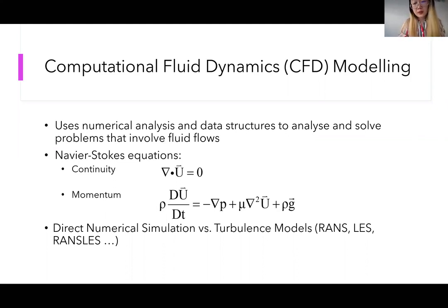And here come a lot of turbulence models. And I'm sure people are very familiar with the Reynolds-averaged Navier-Stokes equations, which is called RANS, and also the large eddy simulation called LES. With RANS, the way that RANS solves the Navier-Stokes equations is that it models the terms that are unclosed in the equations, which are the Reynolds stress terms. And if it's in 3D, you have 6 Reynolds stress components. And that's where the models come in.